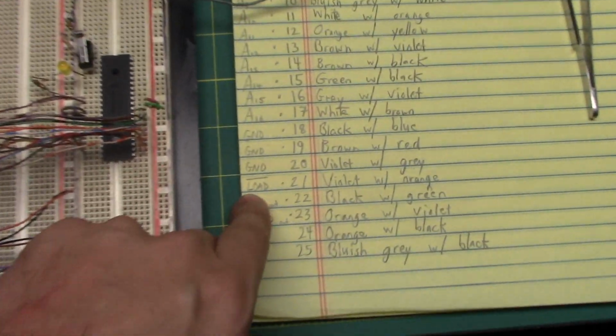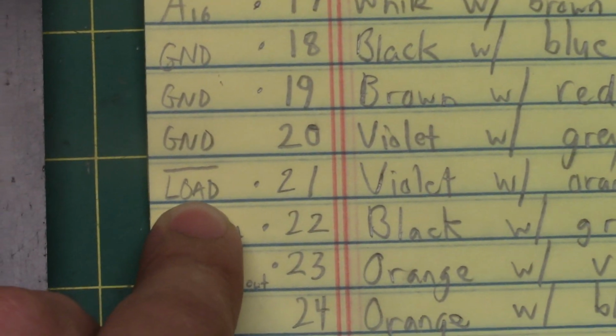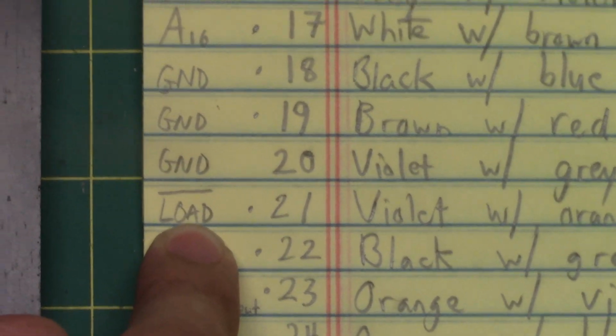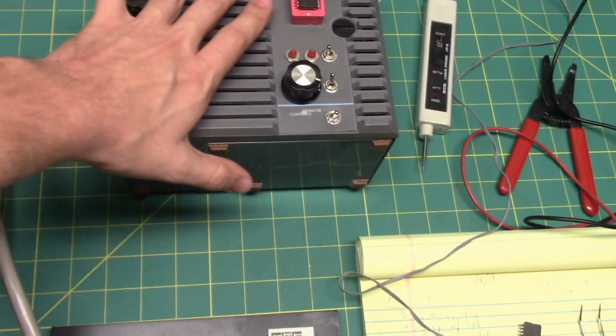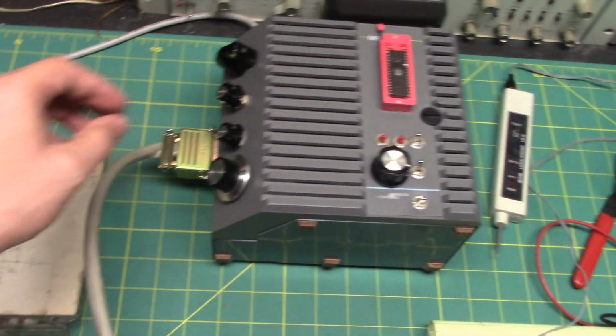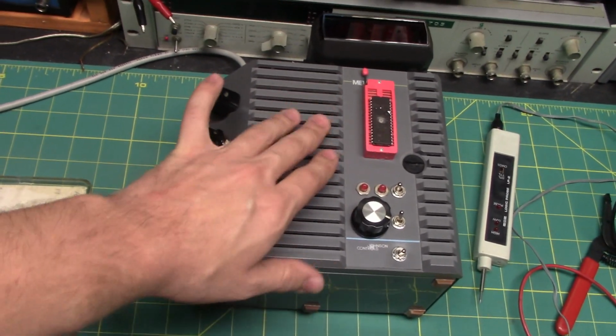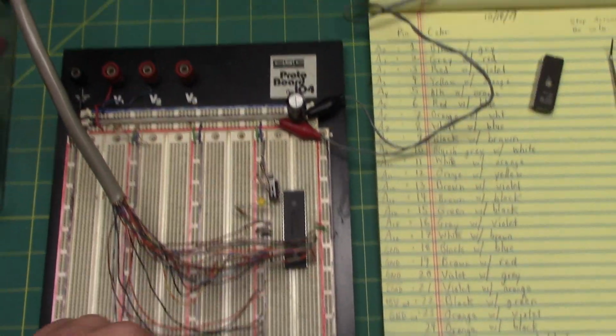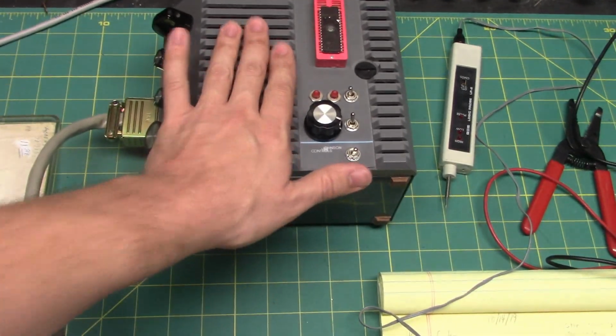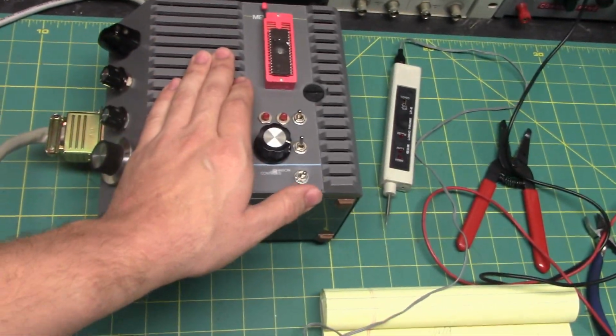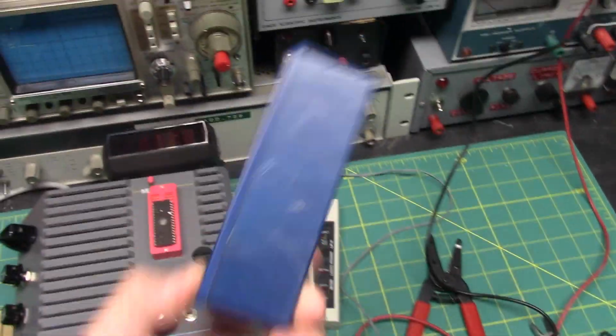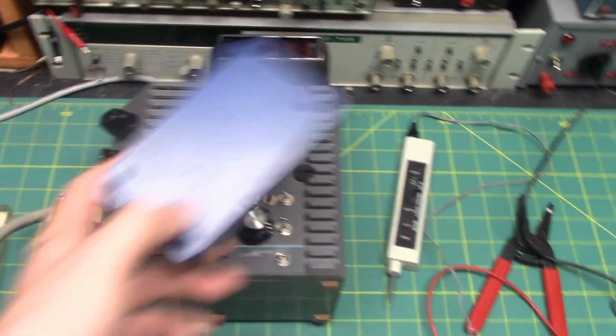The microcontroller sends a signal to this load line, pulling it low, which is the load line of the presettable counters inside, which makes the addresses transparent to what's going over here, and therefore the microcontroller takes control. Also, power for the microcontroller is derived from the EPROM player. The idea is eventually the Talking Thermometer will just be a plug-in module that you stick in the side there.